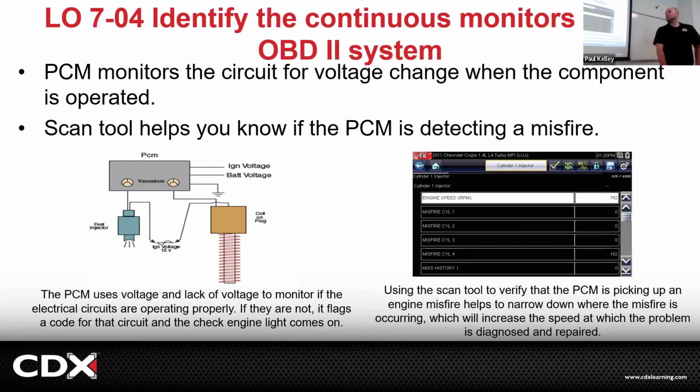Cool. And similar with the ignition coil. If you had an open ignition coil or you had an open wire going to the ignition coil, that'll set a different circuit code. It's usually like primary ignition circuit, open or shorted. So at least you know, hey, it's in there, and it'll tell you what cylinder. So you got a pretty good jump right there. But you guys understand the ECM is the one doing the onboard diagnostics. The ECM is programmed to say, when I do this, that voltage should be that. And if it's not, I set this code.